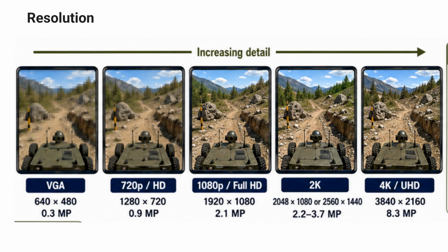For an unmanned ground vehicle, resolution is not about maximum clarity alone. It is about choosing the right balance between detail, field of view, frame rate, latency, bandwidth, storage, and the actual mission requirement.